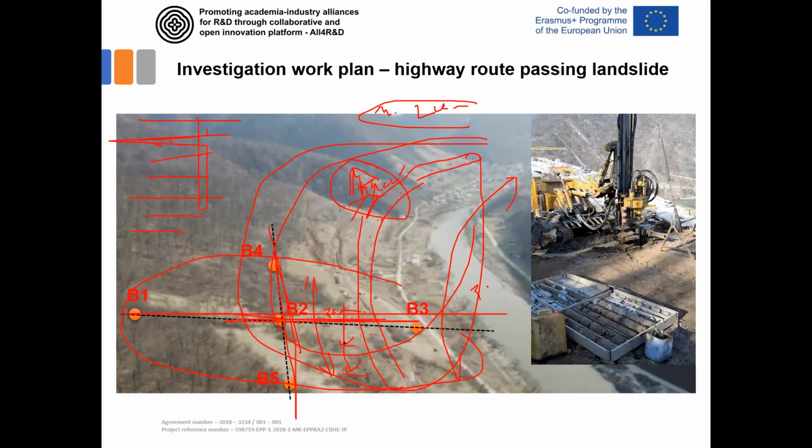You should not follow that when doing a real investigation work program, and the particular values of the borehole locations should actually be defined with an investigation work plan that should be analyzed very deeply, in detail, because it can really influence a lot the construction cost, the changes of construction cost, even the construction period.